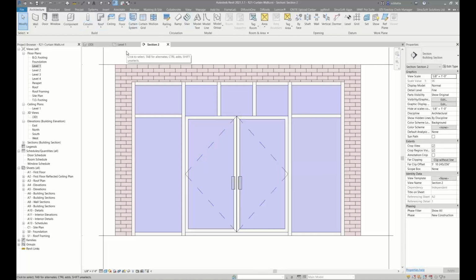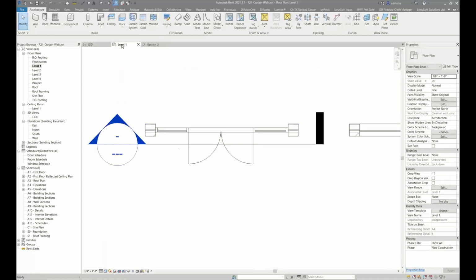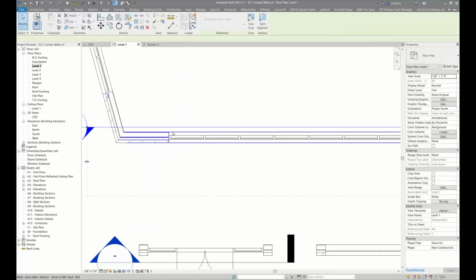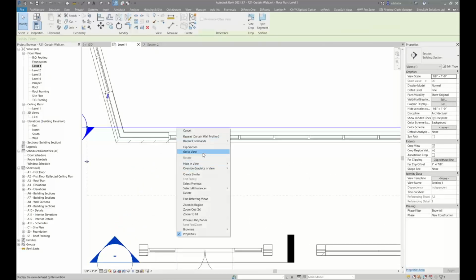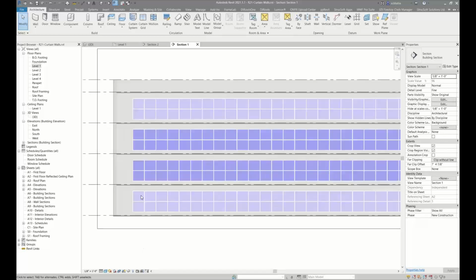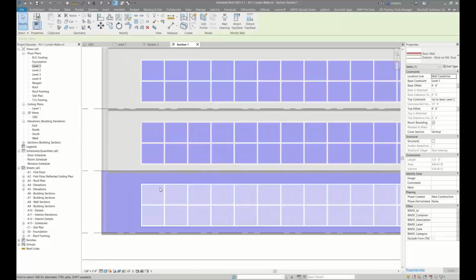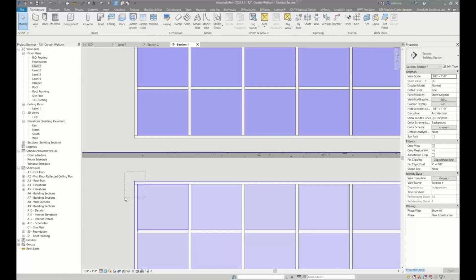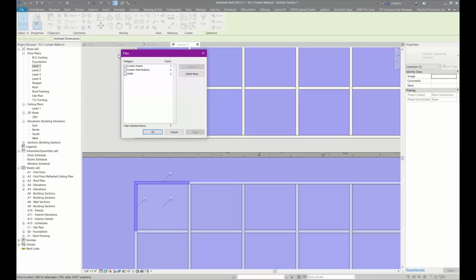And now let's go ahead and show you how you can frame the curtain walls when you are in a build 7991 or older. Okay, so I'm just going to go back here, and I already have a section drawn in. So I'm going to go to view. So yes, this curtain wall is embedding itself inside the wall, but there's no openings here. So if I actually hover over here and I filter this out, you'll notice there's nothing called openings in here, okay?